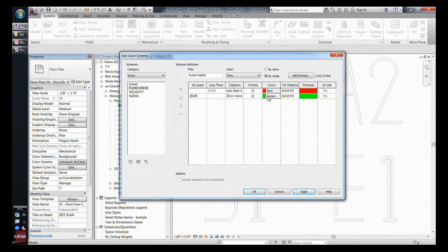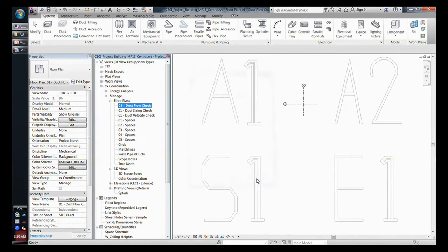So the end result is, you open this view, you look at your entire duct system, and things are either green or red. Red needs your attention, you go and fix things. Could be CFM data missing, could be disconnection of ductwork. Very straightforward, but in my opinion, very valuable for troubleshooting disconnection of systems and also mistyped data.